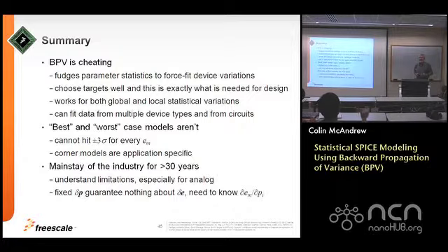Once the sensitivities are based on a linear model, with the assumption of a linear model, you then just directly calculate the variances. The only slight trick there is if there is a slight nonlinearity, the value of the sensitivity depends on the range of the perturbations that you apply to the parameter. And so we actually generate the sensitivity by going from -3 sigma to +3 sigma on each parameter. What that means is that you have to provide an initial estimate of the sigma. Once you've calculated it, you might get a slight difference in the sensitivity. So that's what the iterative part of it is that I described before.